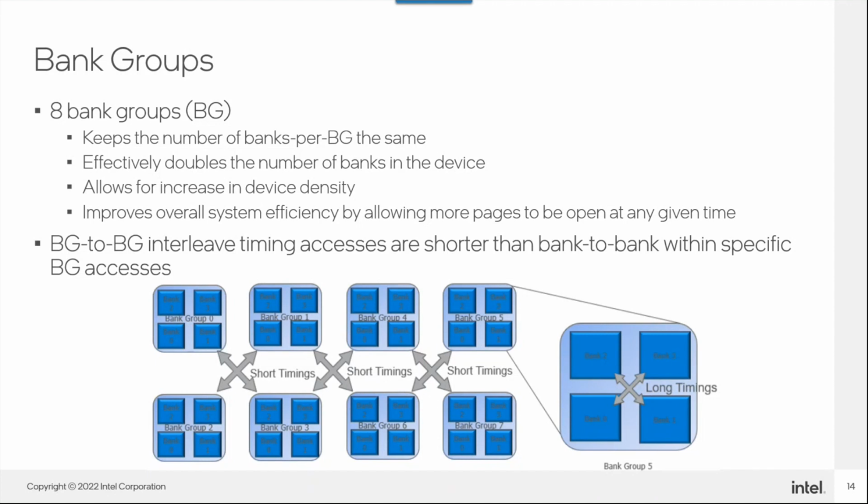Because we have another question in the chat. We got a specific question about Agilex DDR4 usage. If you're using 2 controllers on the same side, DIMM2 and DIMM3 on the dev kit, are you aware of any pinout restrictions that occur when both controllers are instantiated in the design, versus when the FPGA design is compiled with only DIMM2 or DIMM3 instantiated? This person has a resource pinout compile error when they're compiled together, but not when compiled separately. They're sharing the calibration IP as required. Or are there any known issues with using both DIMMs as opposed to only one at a time?